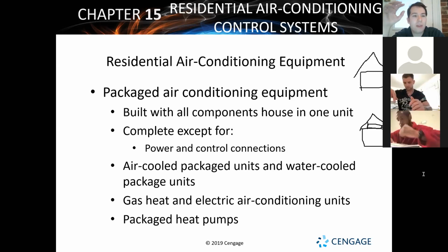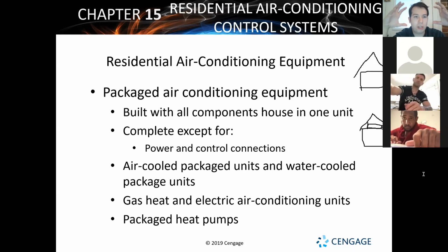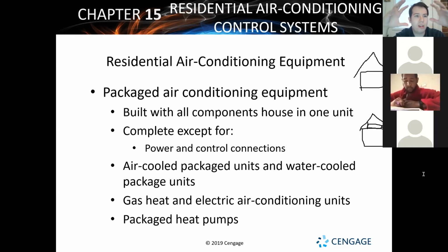So if there's not enough space in the walls of a building to put the air handler, that indoor connection of a split system, where your evaporator coil, your blower motor, and everything would be, that your air comes across, if it doesn't have space for that because the walls are too small, or you can barely fit the ductwork in there and that's all you're going to get in there, this is when you're going to see a package unit used a lot of times, because all you've got to run through the walls is ductwork. That's it. Typically, that's when I've seen it used most often.